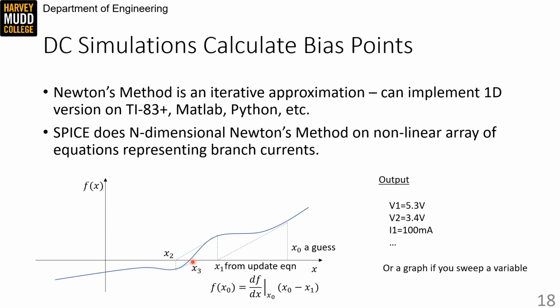There are lots of things to say about Newton's method. For instance, deciding about how many iterations to pursue before you stop requires a bit of thought. However, we don't have time for all of them, and I want you to just take away the most important detail, which is that DC simulations can fail. That's called non-convergence. And you should be ready to adjust your models or simulations to get around that failure.